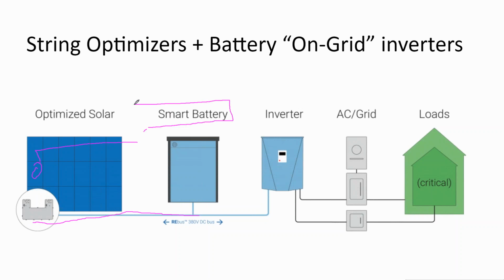Another thing they've done is get with a flooded lead acid battery manufacturer and develop a high voltage flooded lead acid battery, which is cheaper than buying a high voltage lithium ion battery. I actually don't think they're doing it quite right because they're going with a sealed AGM flooded lead acid. Although I've talked with my preferred forklift manufacturer, and they don't really see any reason why you couldn't string up their batteries into much higher voltages.